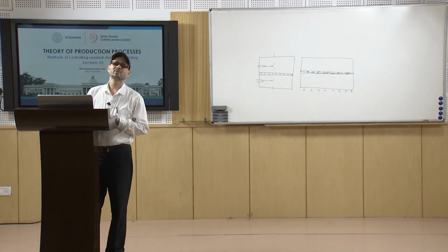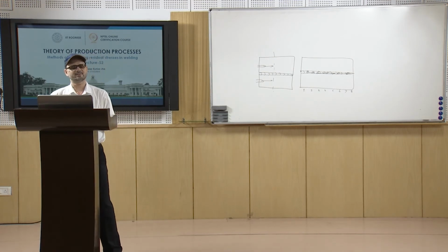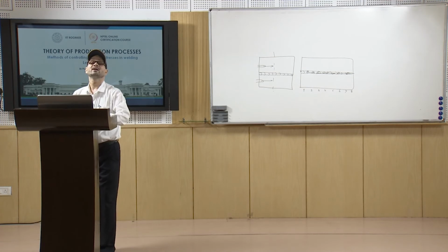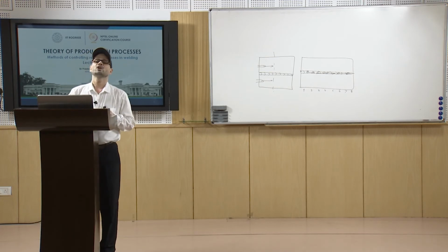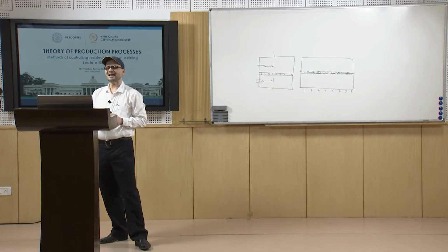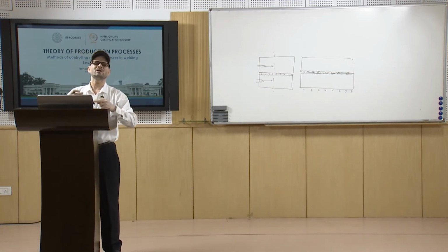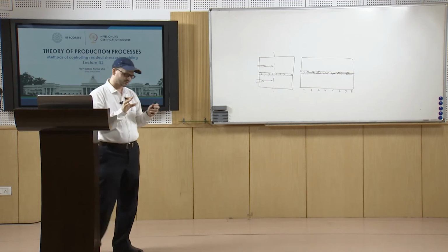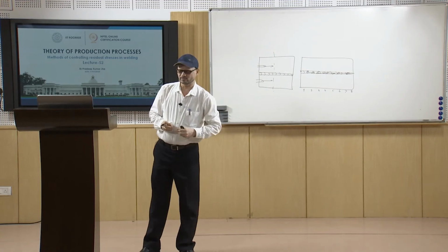Similarly, you have the use of the welding sequence. How you are taking the sequence of the welding operation. Suppose you have the transverse welds and you have the longitudinal welds. In what sequence will you do the welding? In that welding sequence you have to know how to proceed, whether transverse welding is to be done first or the longitudinal welding is to be done first.